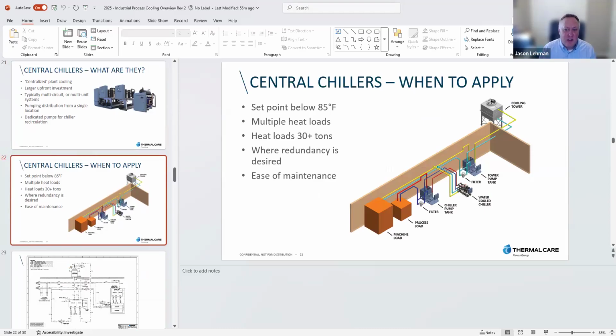Kind of like along the same lines as what Mikey talked about, they're not just a chiller, there's usually a pumping system, depending on what heat load you need. Some people can get away with water in the 90s, so they may use a tower system for that, and then cool a water cooled chiller, and then use chilled water for the heat loads that require colder water.